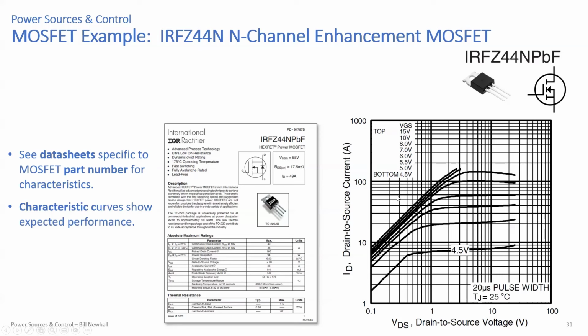Okay, so also notice these are log scales. I have a log scale here for drain current and a log scale here for VDS. Notice these curves aren't perfect. I mean, look at this. This isn't exactly flat, and it has some funny downturns here. So, right, this is what you get when you're dealing with real devices and not cartoon characteristics.